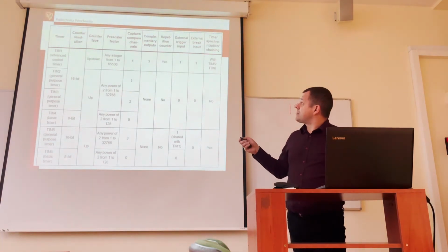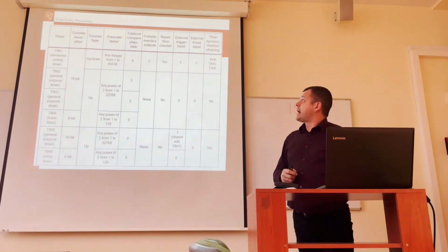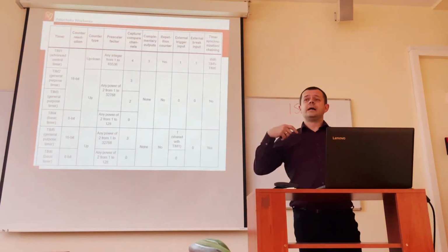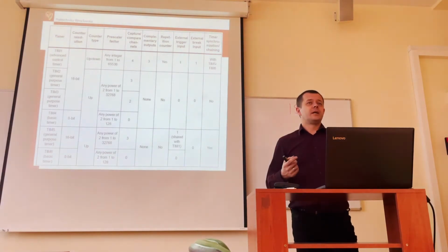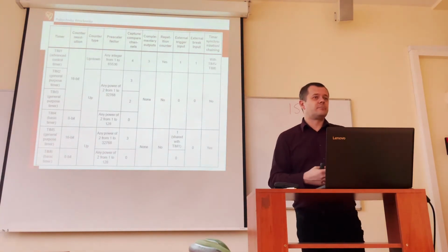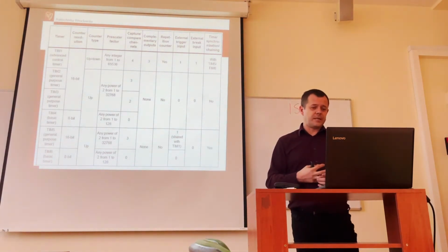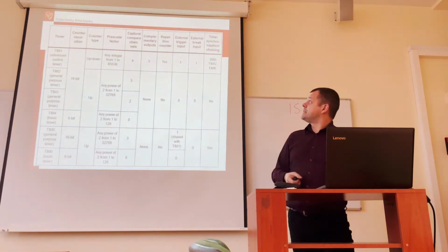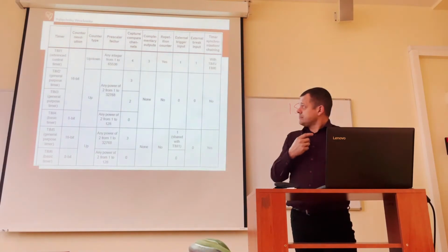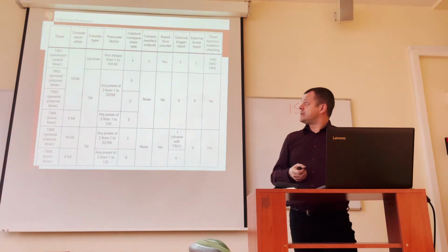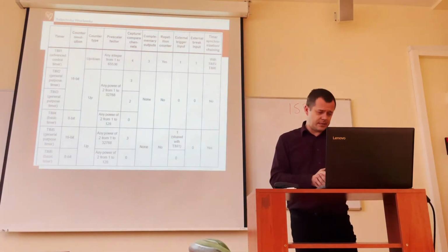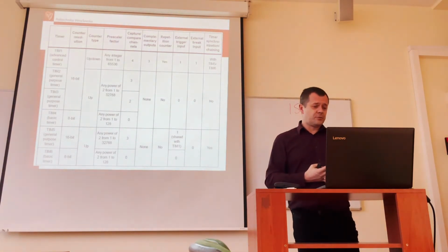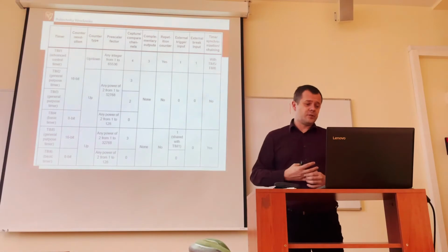In microcontrollers we quite often have capture/compare channels. These are for capturing the events, the signals present on the pins, or comparing the main counter with some preset values.